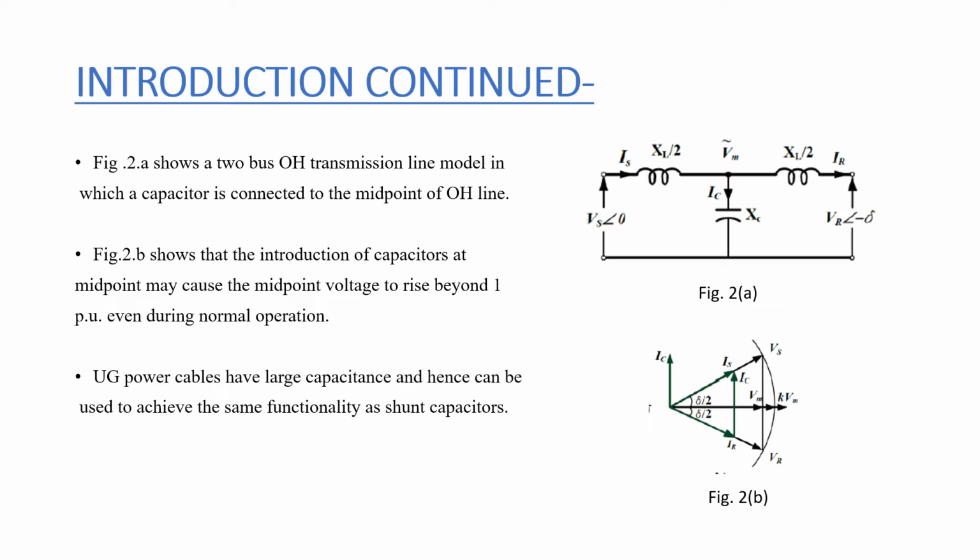If the capacitor is properly designed and sufficient, the reactive power requirement of the line will be met, and there will not be any phase difference between Vs and Is, and between Vr and Ir, which can be shown in the figure below. This results in unity power factor at both the receiving and sending end.